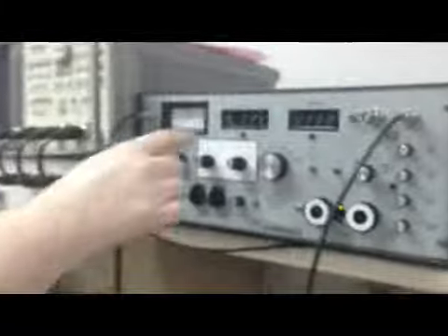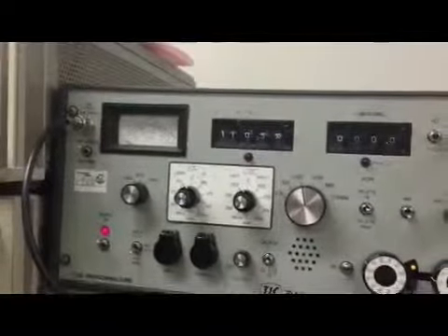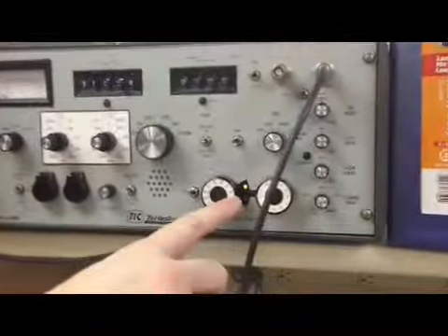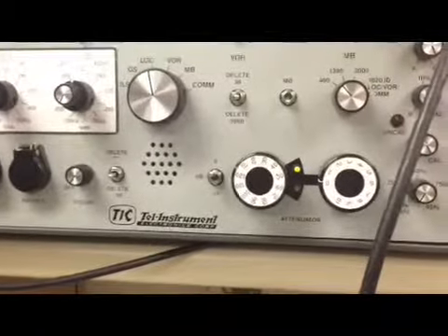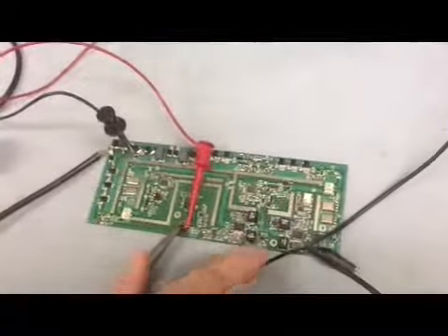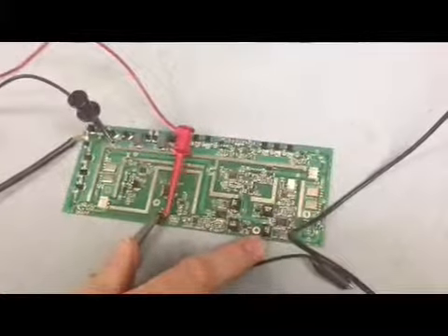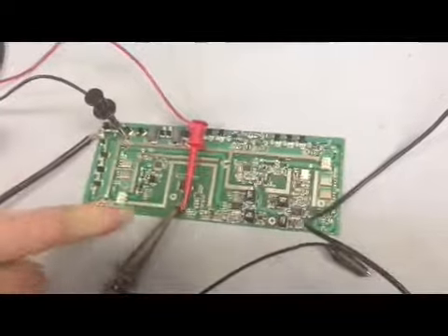This is our generator operating at 110.5 megahertz, and we're putting in a signal at minus 50 dBm. So realistically, we're looking at a relatively small signal coming in. It's going through our cable down into the receiver, going through the receiver, following the microstrip path into the demodulator. The demodulator and AGC are operating within expectations and coming out at that pin on the unit.